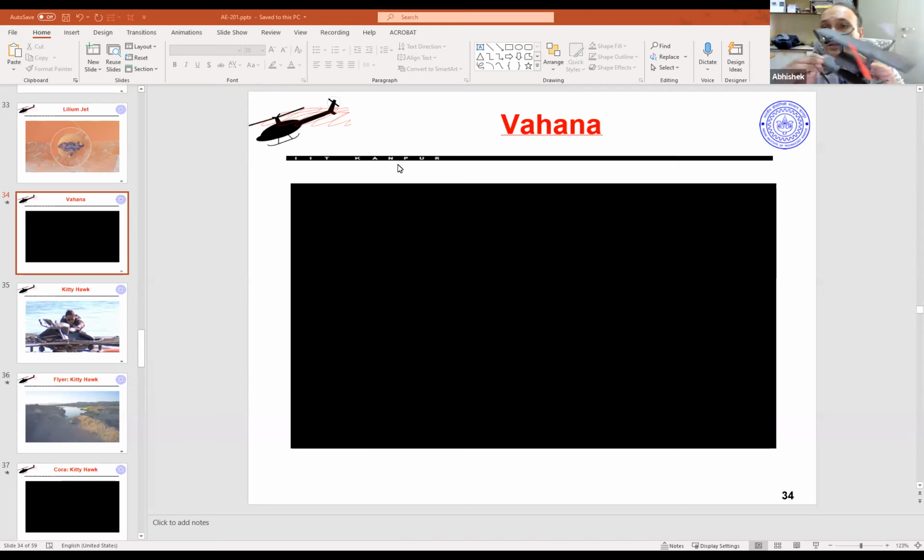Imagine this airfoil, you can see the cross section of this guy, it's an airfoil, right? If I continue increasing the angle of attack, you end up getting higher and higher pressure gradient, the way the pressure changes. If your gradient of pressure is too high because of the high angle of attack, the flow cannot continue to remain attached to the surface of the airfoil.